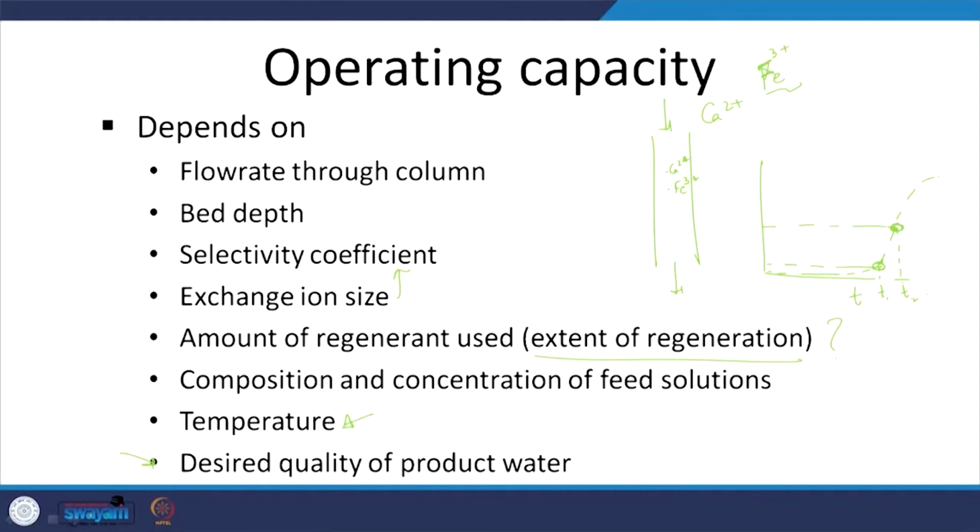And one aspect to note when people come up with different kinds of ion exchangers is the affinity. As in, fine, my resin can remove the calcium or the compound of interest, or chromium and such, but what about all the other ions that are also going to be present in the solution? So we obviously have to look at that data too, as in the selectivity for that particular compound, especially when we consider the background concentration of the competition from the other cations or such.